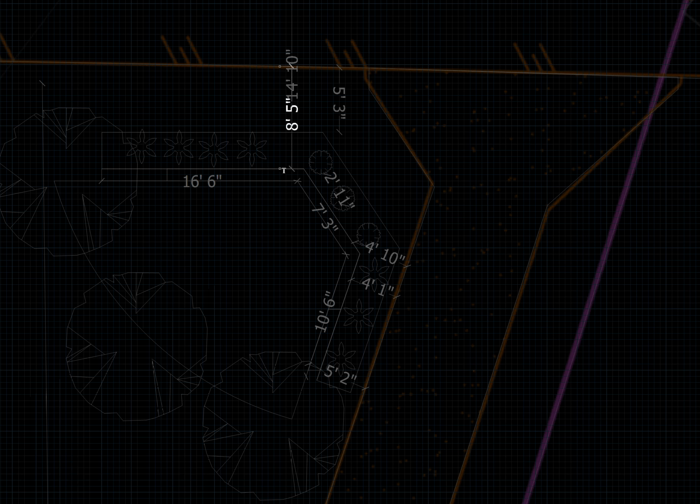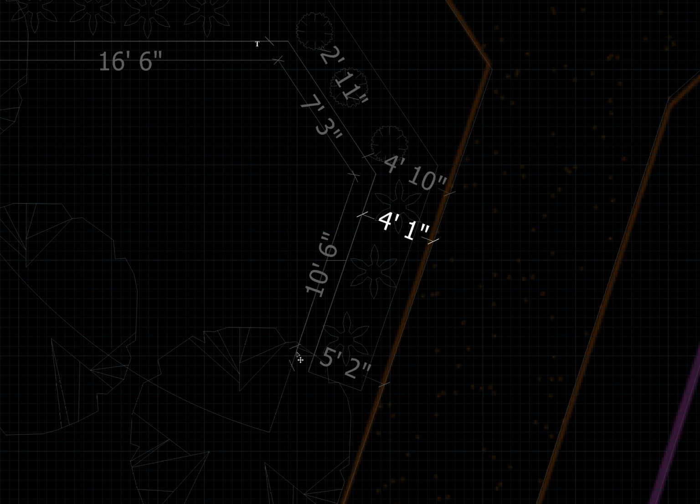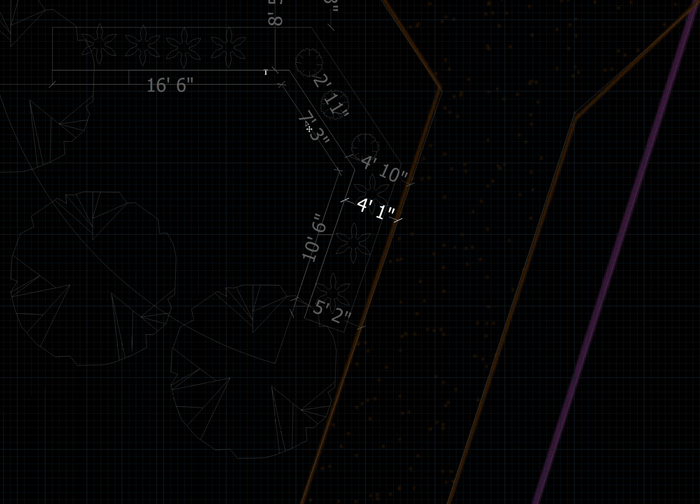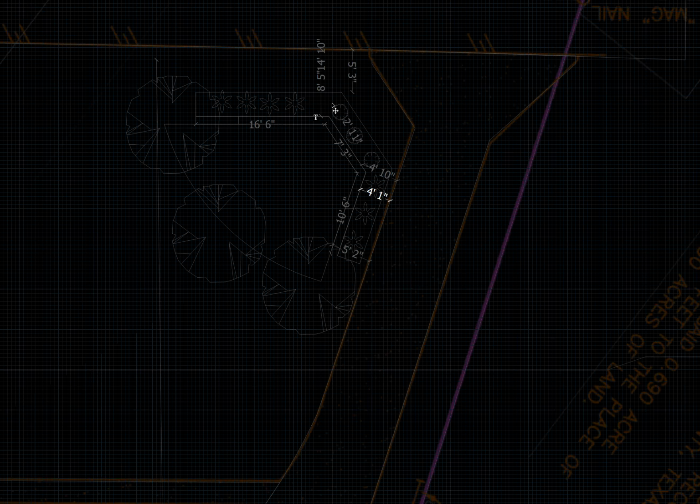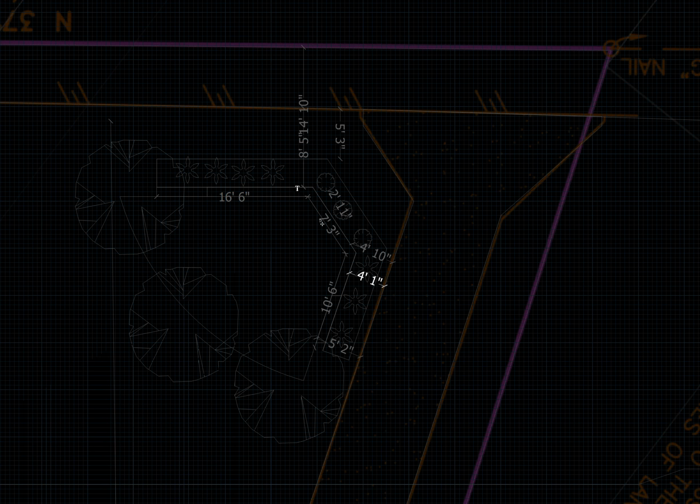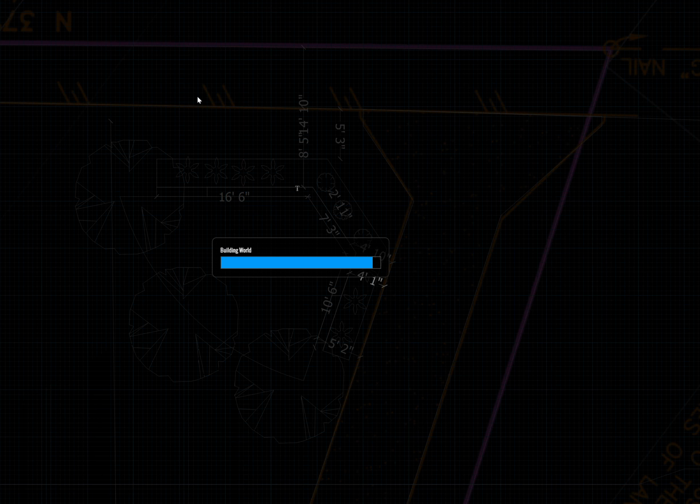This corner right here from the driveway, let me see, I think we're 4 feet. Yeah, 4 feet is what I did. I left a little small grass gap right here, so if you miss the driveway, you have a little play room before you hit the edge. So the wall from the street to the inside of the wall is 5 foot 2 inches. The wall is 1 foot thick. Okay, I think that's all the measurements you need to see. Pull back out.